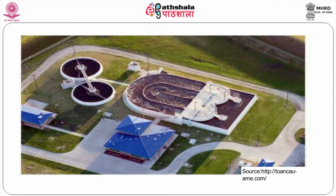By retaining biological mass for longer duration, most of the sludge will enter into endogenous phase of respiration. So, sludge is partly stabilized. In addition to carbon oxidation, we can achieve nitrification. The partly stabilized sludge can be dewatered by providing dewatering facility at the downstream side of the reactor.